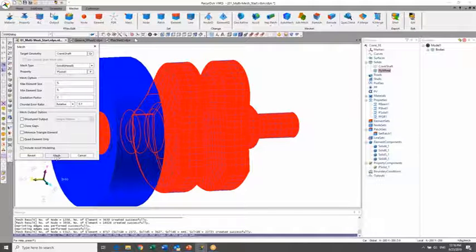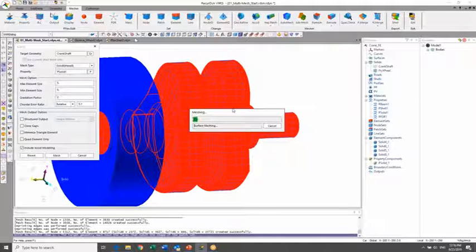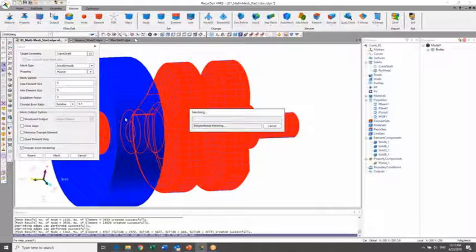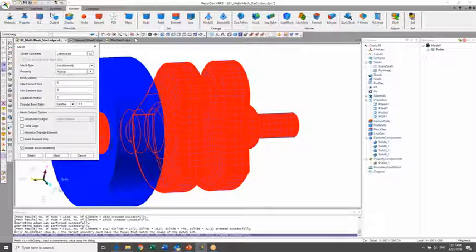And here is where I just click Mesh, and had I not exited out previously, the patch set would line up with the other geometry, and based upon that imprint patch set, the nodes would perfectly line up with both geometries.